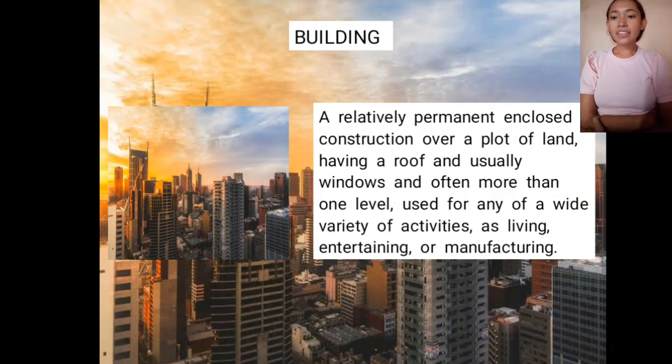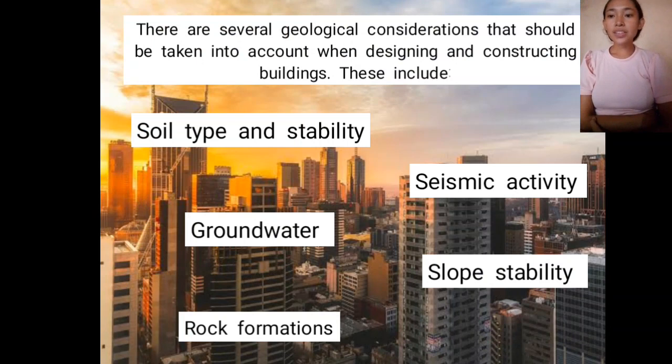Building. A relatively permanent and closed construction over a plot of land, having a roof and usually windows, and often more than one level, used for any of a wide variety of activities such as living, entertaining, or manufacturing. There are several geological considerations that should be taken into account when designing and constructing buildings. These include soil type and stability, second, seismic activity, third, groundwater, fourth, slope stability, and fifth is rock formations.